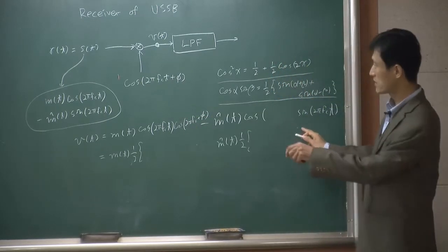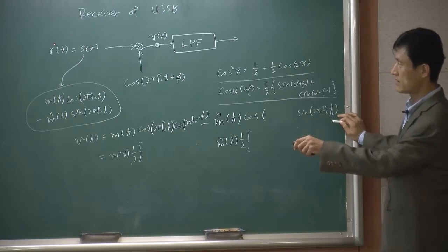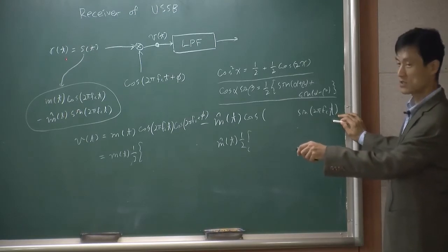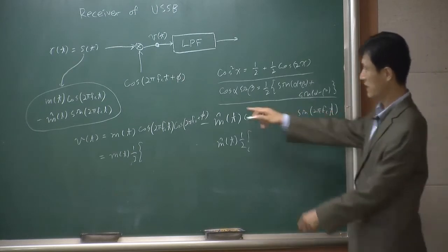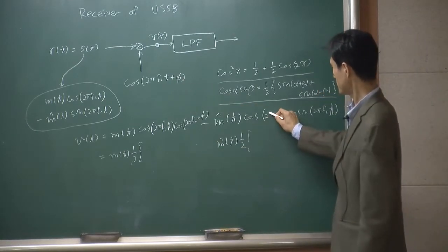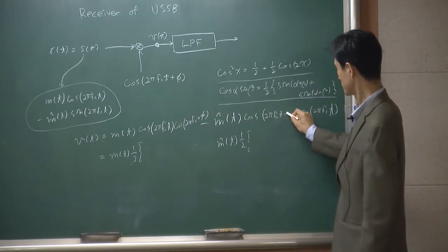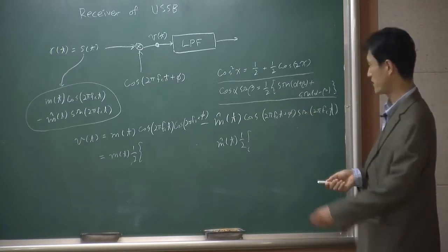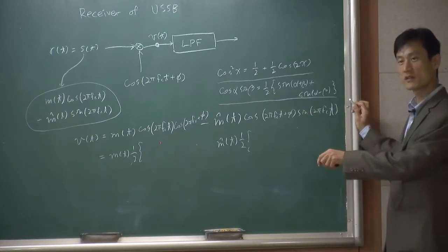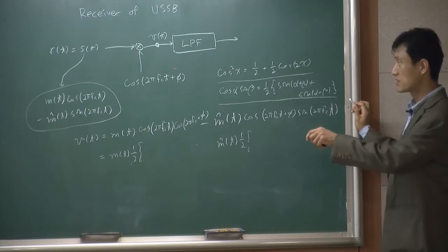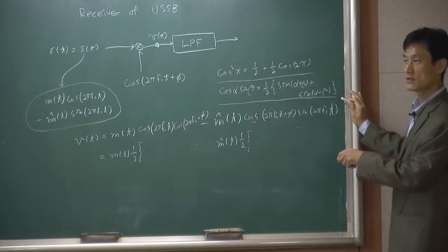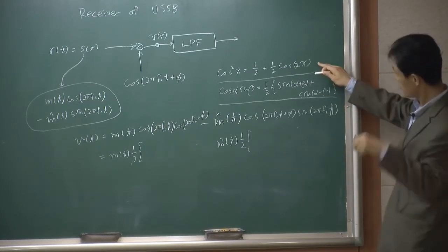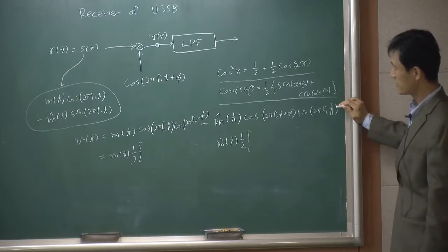Same thing, we originally have a sine multiplied by the transmitter, and you are multiplying by cosine in the receiver, but that cosine has the phase mismatch. So that's what you have as a VT. When you have a phase mismatch like φ, this is going to be your VT. And you can still use the same identity.